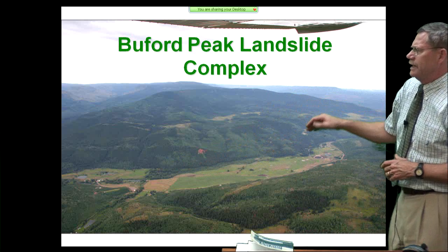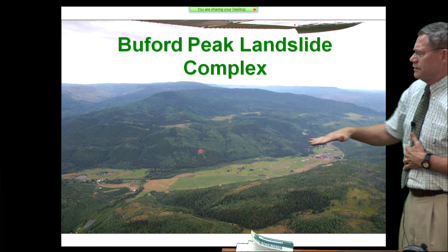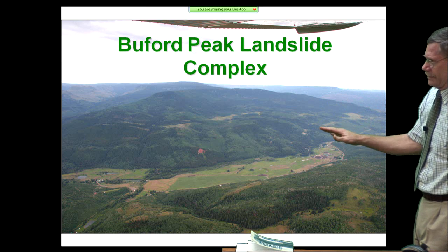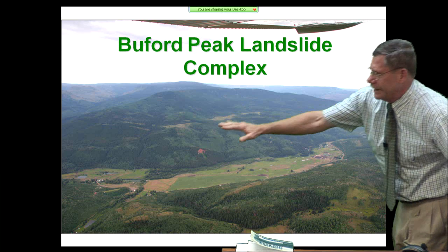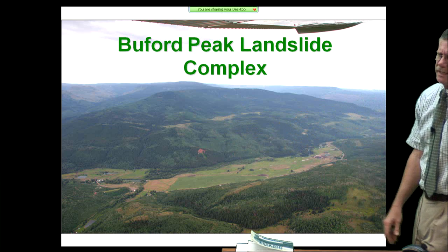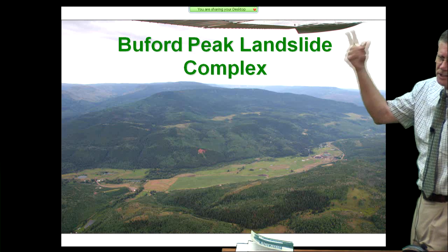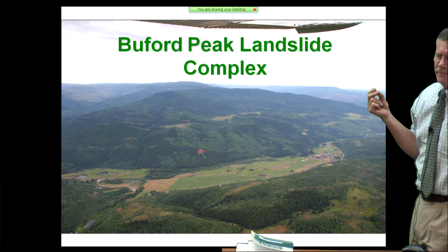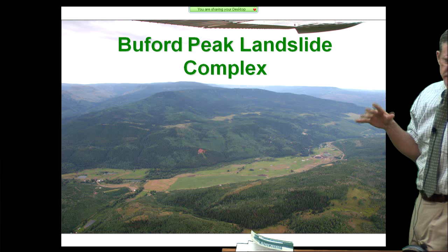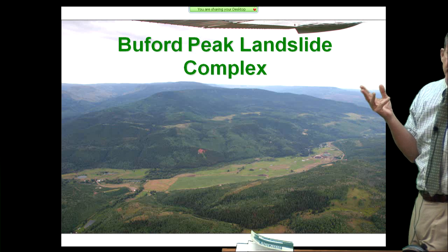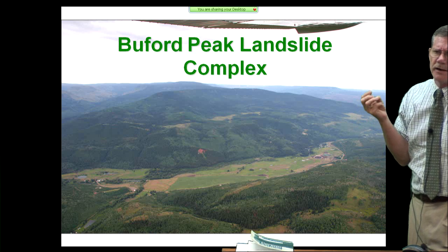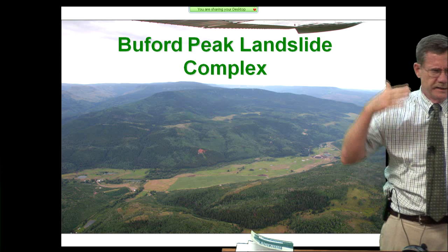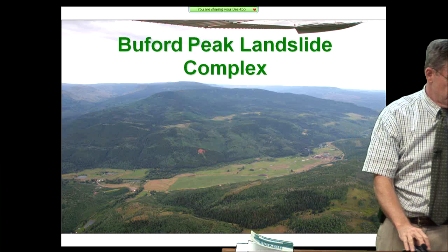This Flatiron section of Colorado is just covered with gargantuan landslides like this because of the volcanic ash deposits in the Tertiary volcanics. Ash invariably weathers to smectite clays. Smectite clays have very, very low friction angles, typically 2 to 4 degrees, so you get very, very large landslides with them.